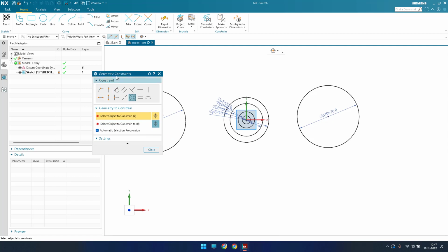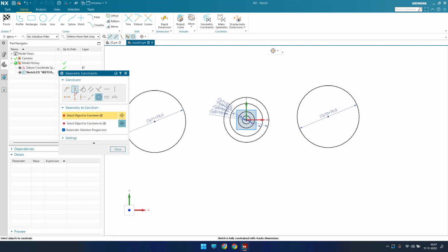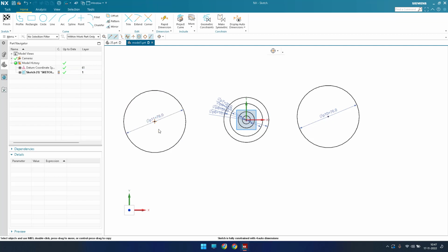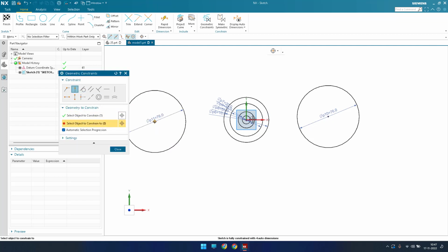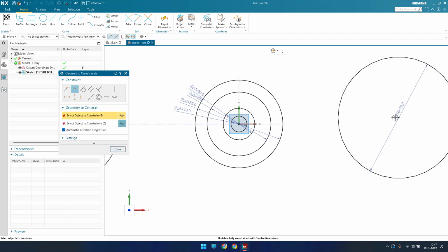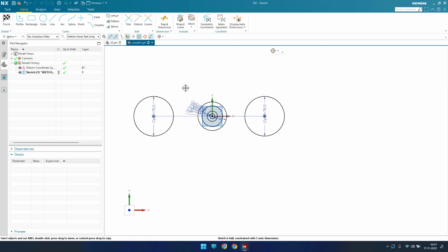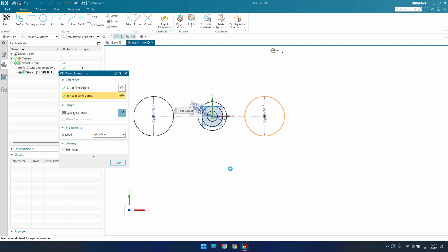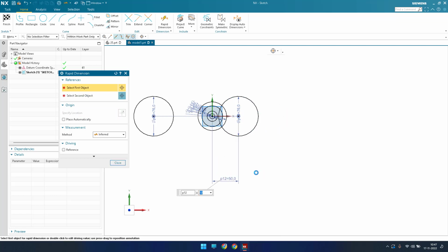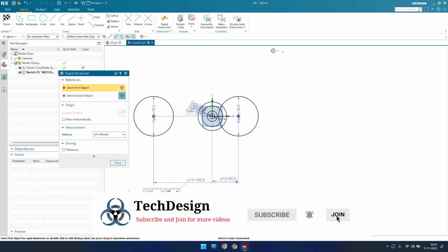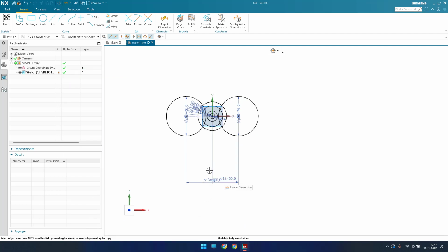This circle should lie on this x-axis. So press C, point on a curve. This point should be on the x-axis, and this point should also be on the x-axis. There is some distance here. Press D for giving a distance. From this to this it is 50 mm, and from here to this it is 100. So it is mirrored. Now it is done.